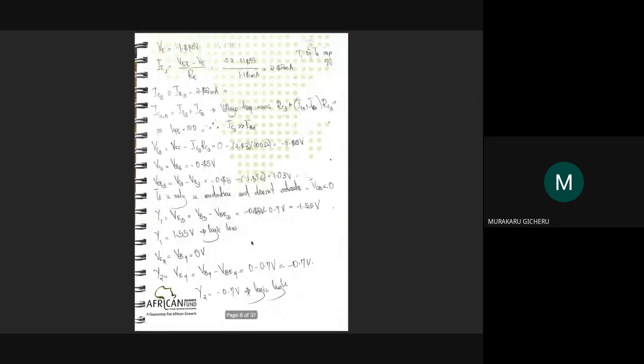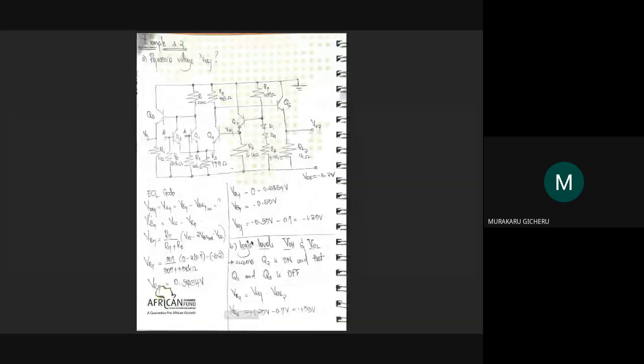So if you go to how ECL works, the notes are here. You'll go through them. So basically, the fundamental circuit of the ECL is a NOR gate. And if you add the extra output stage, you'll convert it to OR.